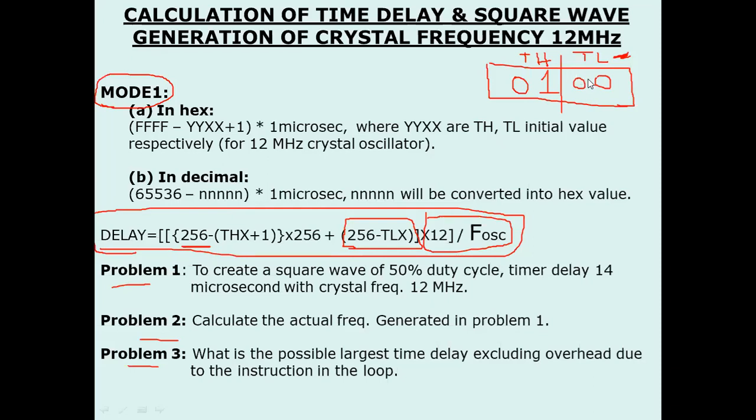So that is not the case. I am telling you, every timer or counter operation, the value will be incremented by 1. Here the increment has been done 2 times. So FE plus 1 is FF, then again plus 1 is 00, and TH will be incremented by 1.